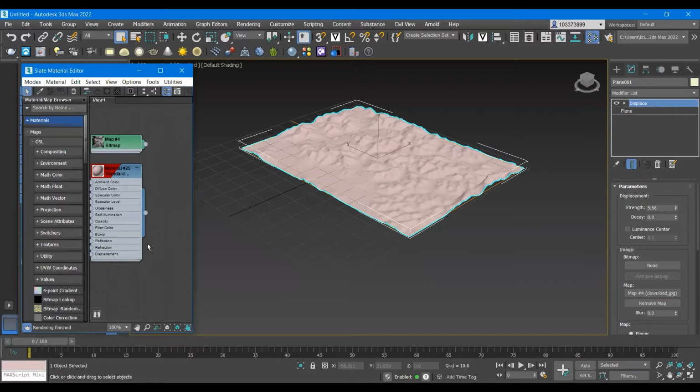When you already have that small window for V-Ray, you just need to connect it to the plane, where you can see the color will change to black. So you just re-plug in the initial material setting. And for V-Ray, you have to click on V-Ray Sun and set it anywhere you want. Then you click on render setup, and then you hit render.